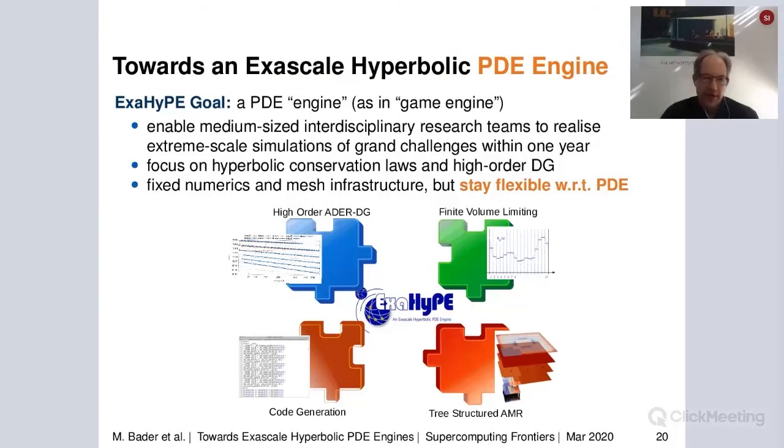It's using code generation in a heavy way to achieve high performance on nodes and multiple nodes. And in contrast to the SeisSol numerics, it's addressing nonlinear schemes as well. If you're doing a discontinuous Galerkin for nonlinear problems, you require a limiting procedure, and there we use so-called a posteriori limiting that combines DG with a finite volume scheme that is robust for nonlinear effects.